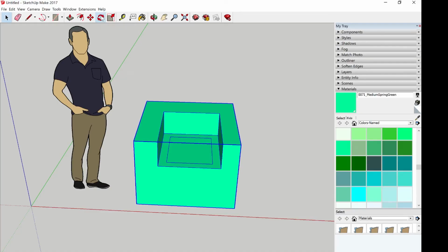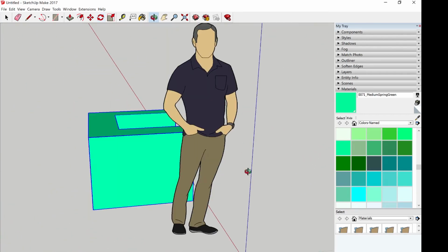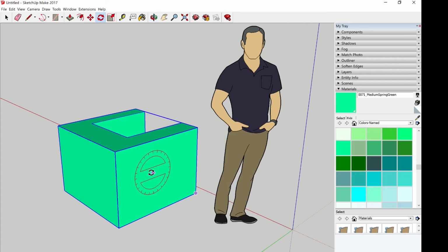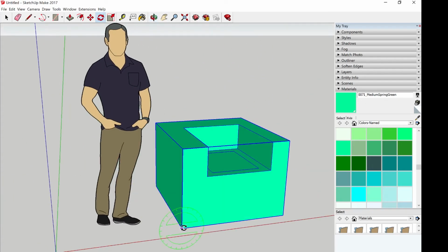Then after that, there's rotate. For rotate, first you have to select your plane and origin. So if you're rotating along the blue point, perpendicular to the blue axis, the protractor for the rotate function will be blue. And if it was perpendicular to the red direction, it will be red. And same for the green. I'll show you what it all looks like.